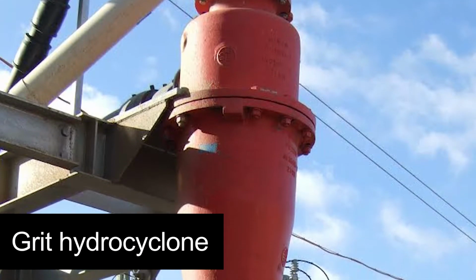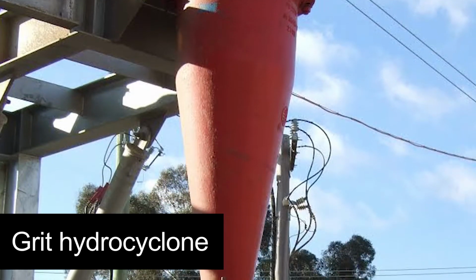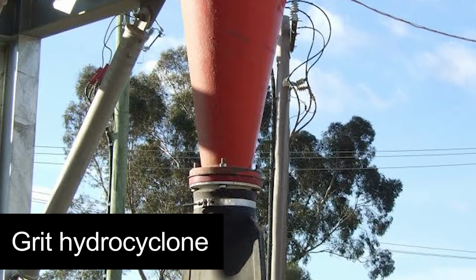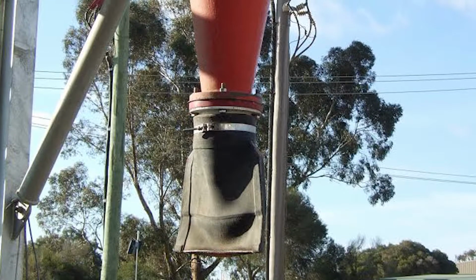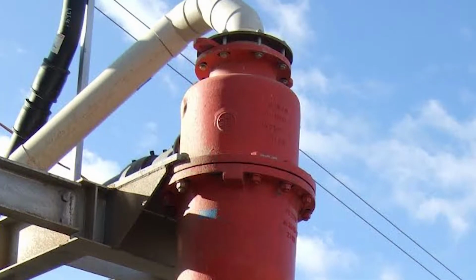Hydrocyclones are used for separating dense solids such as sands and grit from water. Wastewater is pumped into the conical end, creating a swirl, causing denser particles to be flung to the inner wall and slide down to the bottom discharge for dewatering and disposal. Finer solids remain in the majority of the wastewater stream, which is discharged near the top.